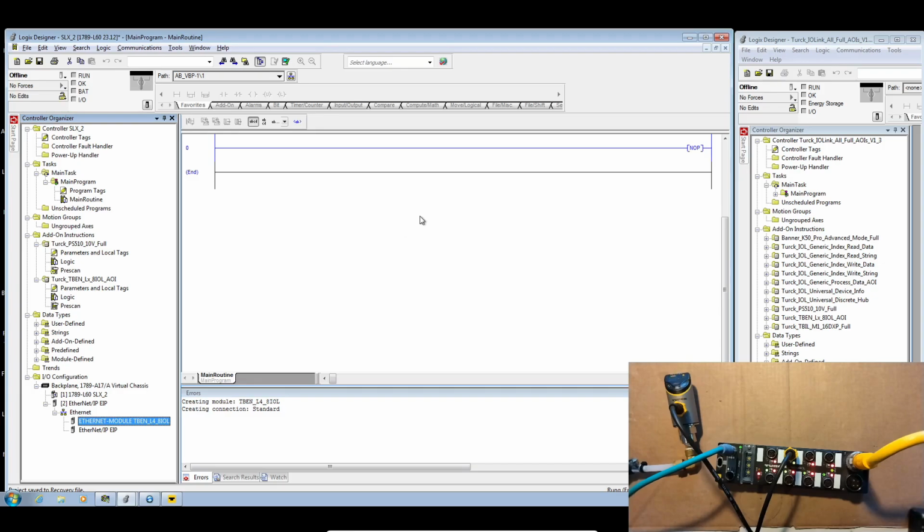And let's jump over to the Allen Bradley software where I have imported a L5K catalog file that has all of the add-on instructions that we need in order to make this work. An L5K is just imported as an existing project, and it creates an ACD file on your machine in the version of the Rockwell Studio that you have. What I've done is I've already dragged over the L4 8IOL device and put it in my Ethernet IP network, and I've dragged over the 8IOL AOI and my PS Plus AOI.